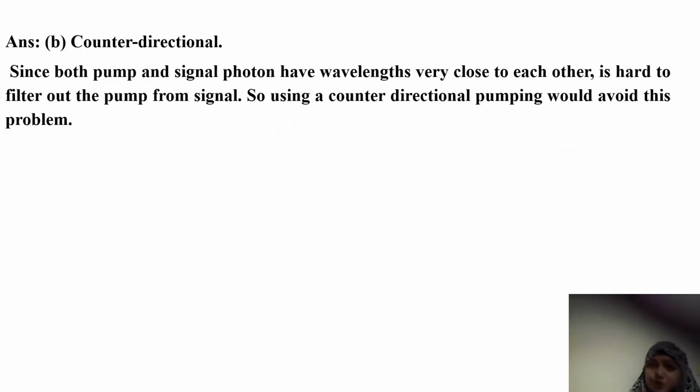Because both the pump, which is 1480 nanometers, and the signal photon, which is 1550 nanometers, have wavelengths very close to each other. So it will be very hard to filter out the pump from the signal. So we have to use a counter-directional pumping so that we can avoid this problem.